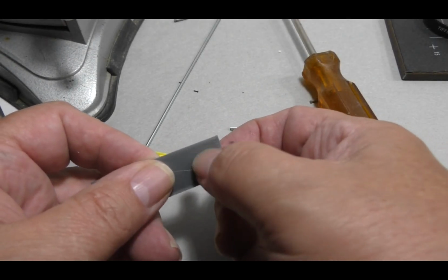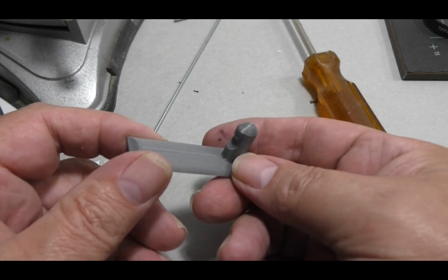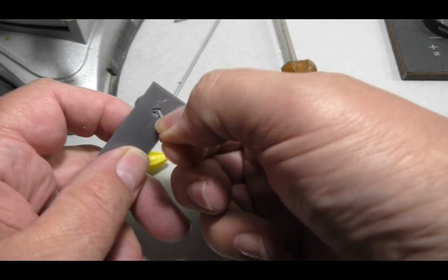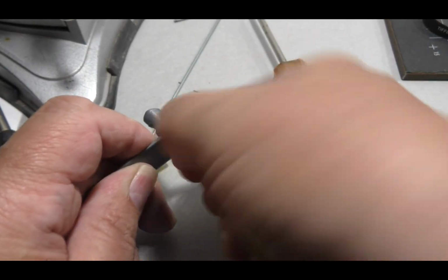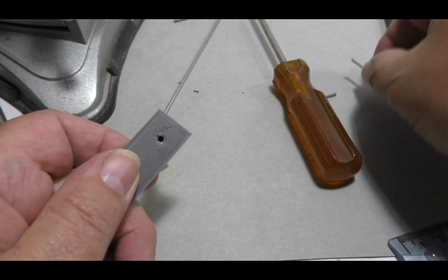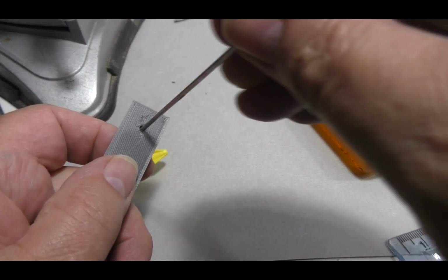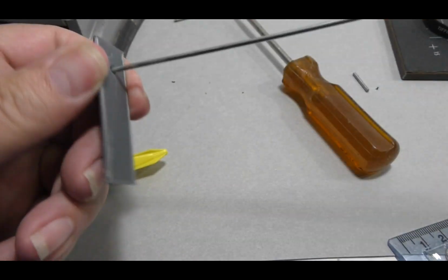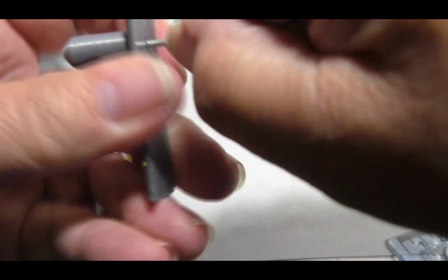Welcome to the bonus section on inserting the reinforcing steel pin. We made the hole for the pin 2.75 millimeters in diameter in the design, but we're going to fit a 2 millimeter steel pin into the hole. Why did we use such a large figure? Because when you're FDM printing a hole, the smaller it gets, the more some inaccuracy tends to creep in, usually in the form of making a hole smaller than what was designed. Also, we need a little bit of room for the glue.